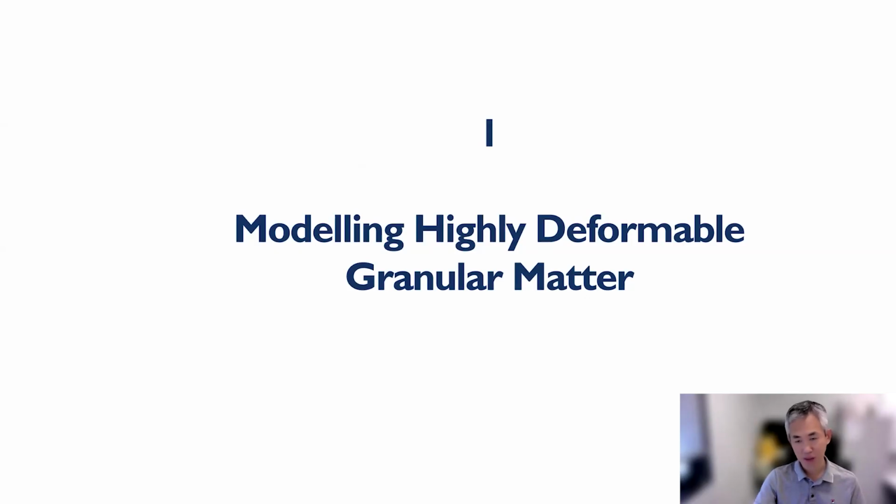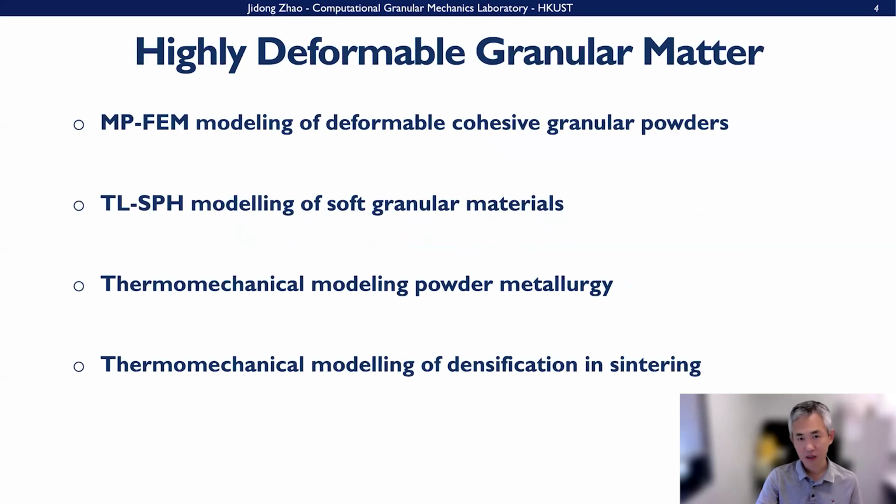I'm going to introduce the background first, and then different ways we can address it. For example, I introduce multi-particle FEM modeling, and also total Lagrangian SPH modeling of this deformable matter, and then address thermomechanical coupling for powder metallurgy, and also for densification in a sintering process here, right?